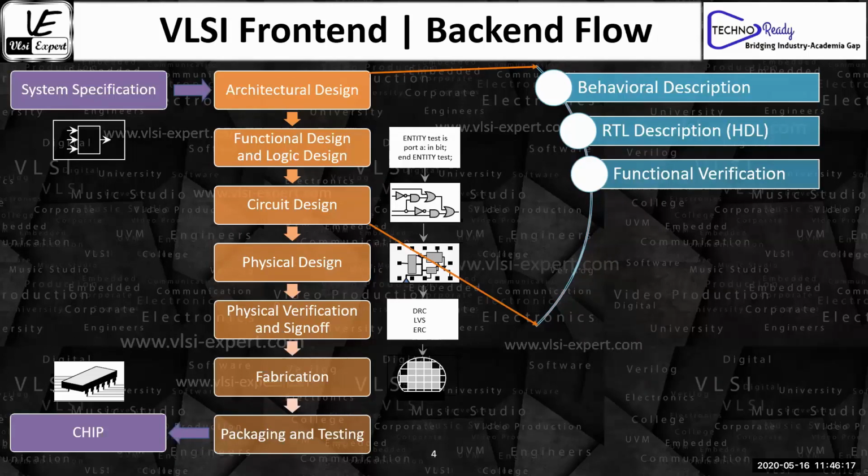Okay, so there is a question. Just one question: will fabrication check for the DRC rules? Yes, Jashwant, they check it. Foundry people check for the DRC, and they will tell you that these are the problems in your design from the DRC perspective, not the LVS perspective.